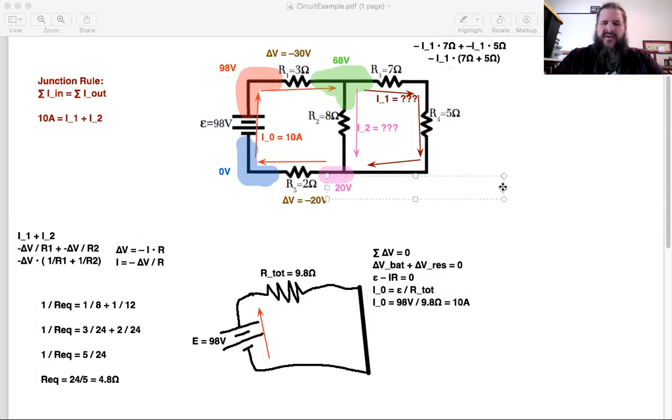But it's not just the voltage at that one point, because any point connected by just wire has to have the same voltage. So it's really not just this point here, but all the points connected to it by just wire. This entire shaded in region is all at the same voltage. Any points connected by just wire are sharing the same voltage. And the important thing about that is we now know the voltage difference across resistor 2. What's the difference in voltage from right before resistor 2 to right after resistor 2?